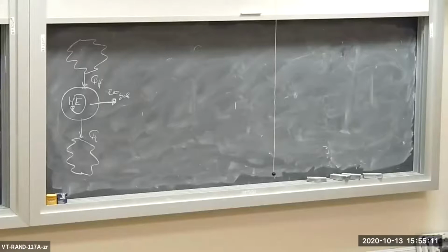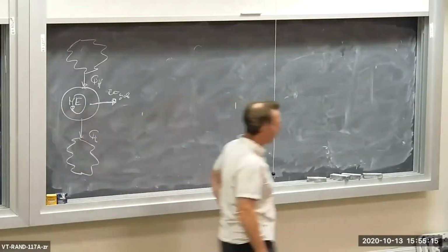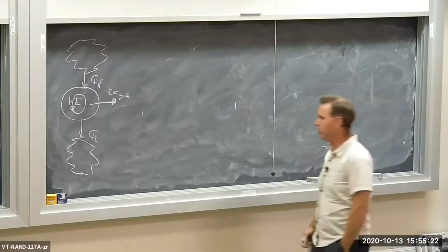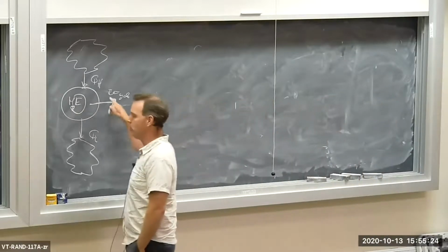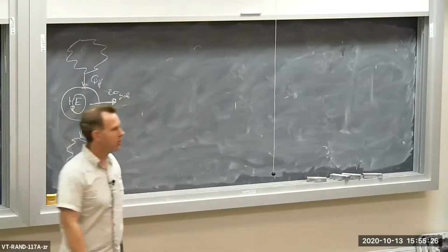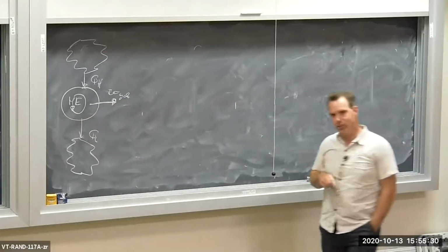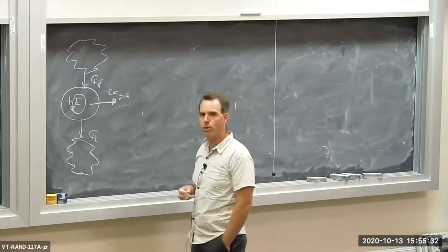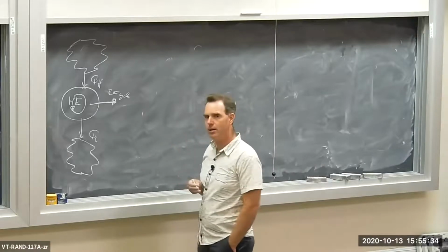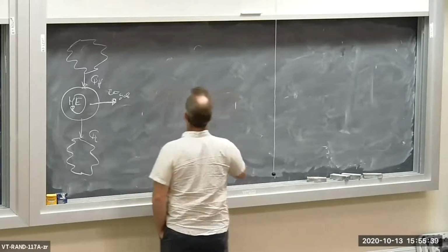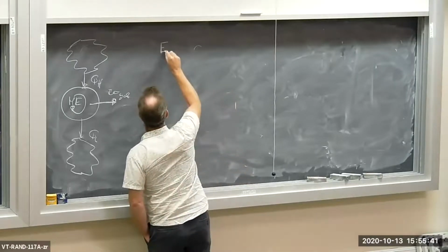Okay, let's say we have a cyclic device. It's a heat engine extracting heat from some high temperature reservoir and rejecting heat to a low temperature reservoir. This thing operates in a cycle, so it produces work, W cycle. So let's analyze this cycle using the energy balance and the entropy balance and see what we get. So how about the E balance?